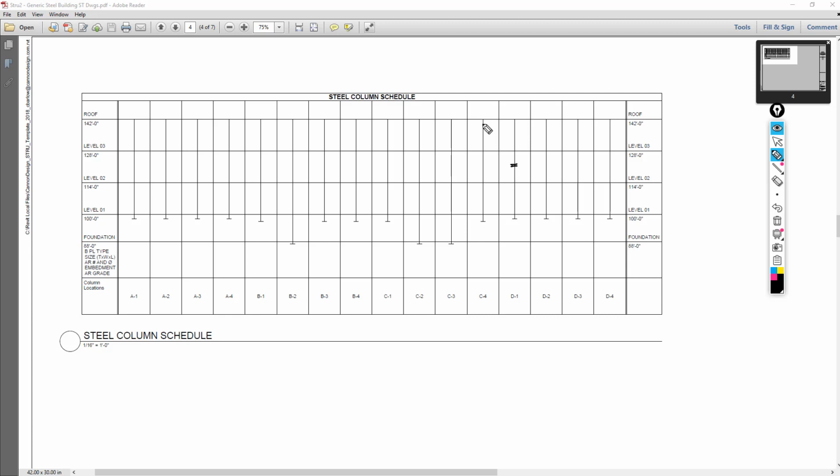So typically, steel columns will be one long continuous piece, so long as it is around 40 to 50 feet or less. However, if it gets much taller than that, say you have a few more floors added on beyond this roof level, there will likely be some location for a splice.